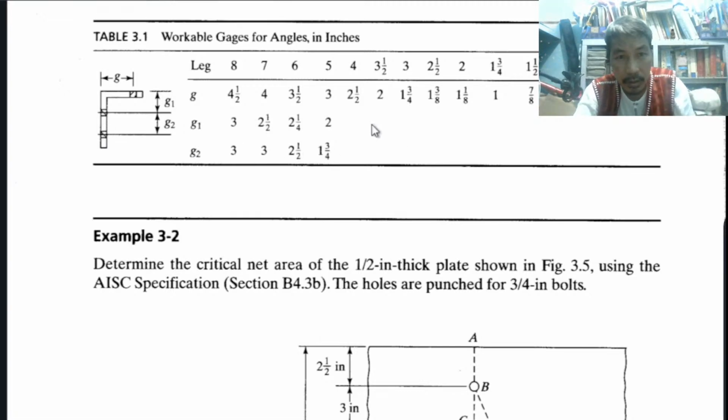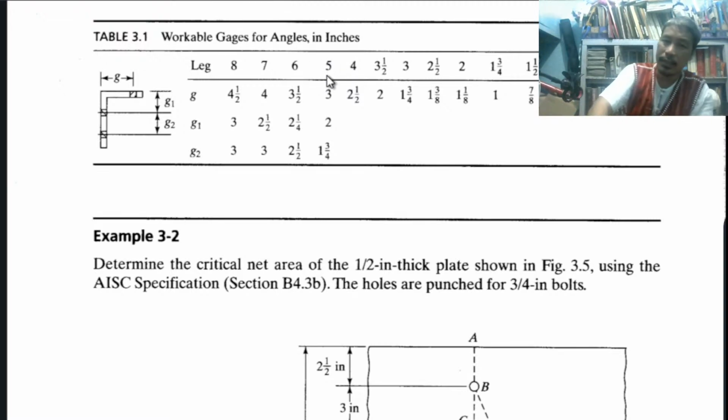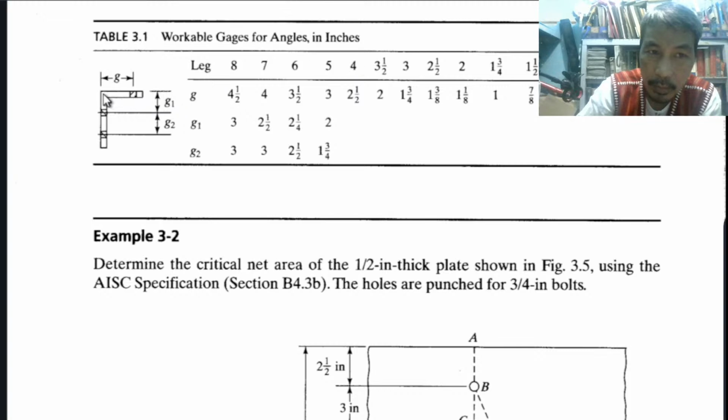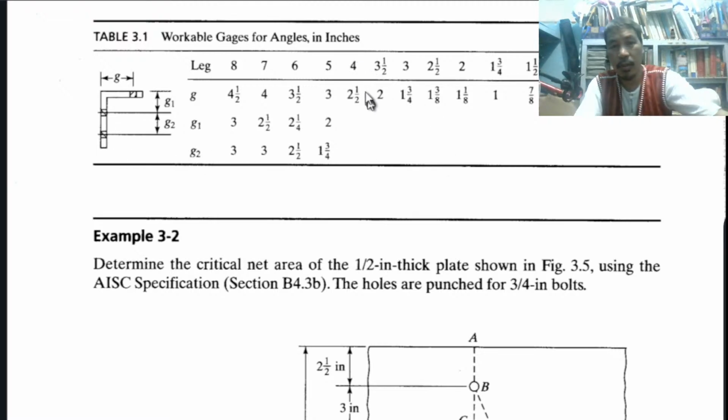Only for 5 inches can we have 2 holes on the other side. So for 4 inches and below, meaning from this point to the edge is 4, for 4 by 4 we have 2.5, 1 hole on one side only. Very important to take note of that.